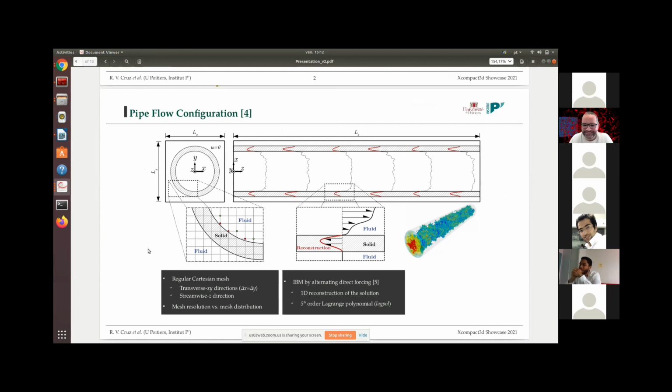Yes, well, because these points are found very close to the wall, and because of our IBM, we cannot consider our mesh size in the CFL condition to predict our time step. Theoretically, you have to consider these close nodes, but it's still not the closest ones. It's something that we don't understand very well, to be honest. We don't have this answer. I was speaking to Eric about that today. We are still trying to understand, but we know that the IBM is responsible.